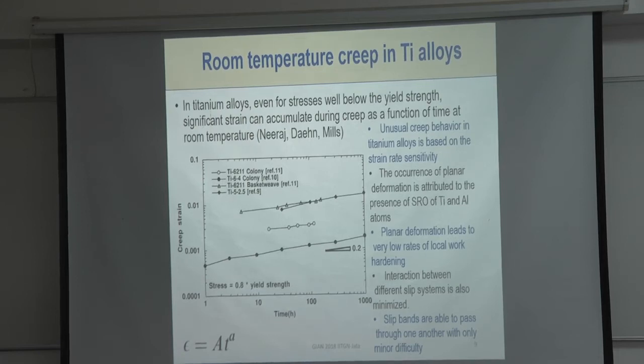4.2%. No, 0.04%. That's the creep strain you're getting in the most bottom one, which is the titanium 6-4. So it's not a whole lot, but it is there, 0.04% creep strain. And if you have a good extensometer, a capacitance gauge, that's what they use most of the time to get those kind of strains. They can put the capacitance gauge outside the furnace. You don't have to put it inside the furnace. You can put it outside the furnace, and it's very accurate, very, very sensitive. Okay?